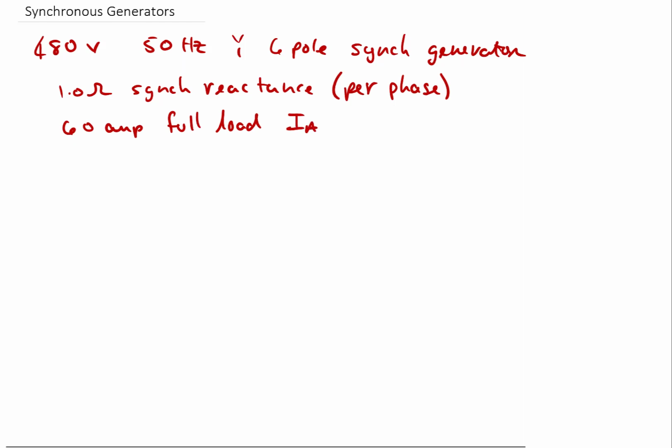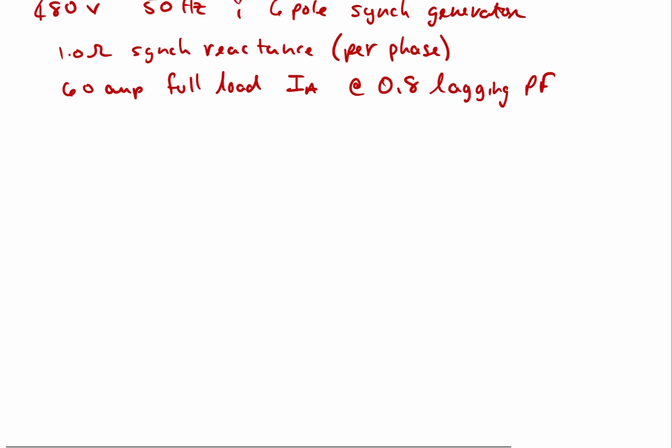And that is going to be at 0.8 power factor lagging. We have some losses. We have a 1.5 kilowatt loss for friction and windage.